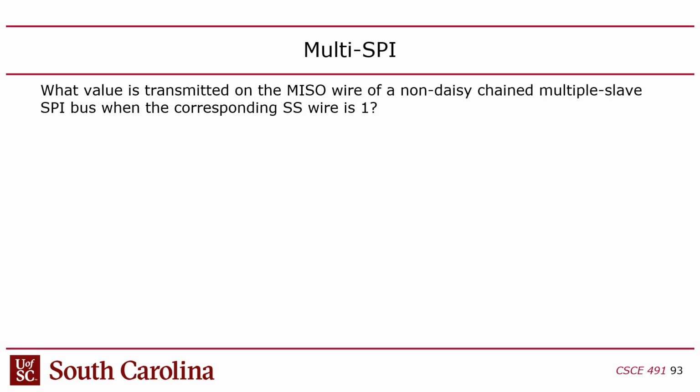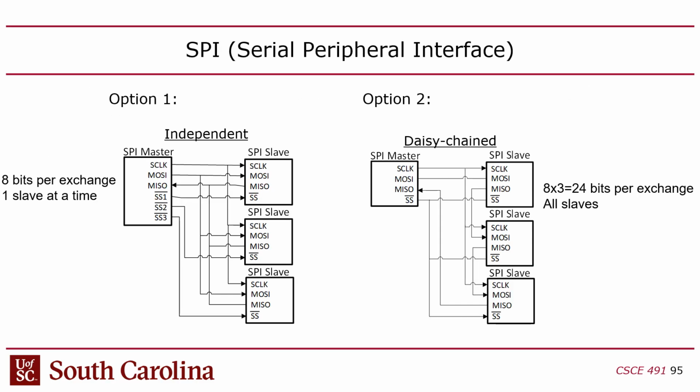So typically SPI is point-to-point, you just have 2 ends of the connection. However, I've heard of ways that you can have multiple slaves. I've never seen it done, ever. But the rumor is that you can have multiple slaves, and there are a few ways to do that, in theory. One way is you can take the clock, MOSI, and MISO, and those can be shared by all the slaves. But then you can have separate slave selects for each one.